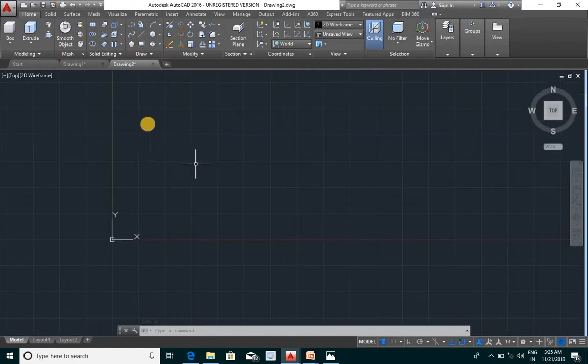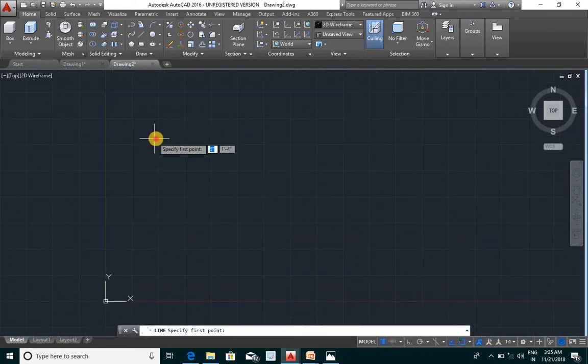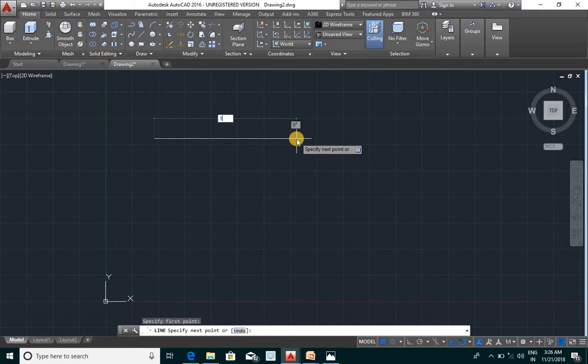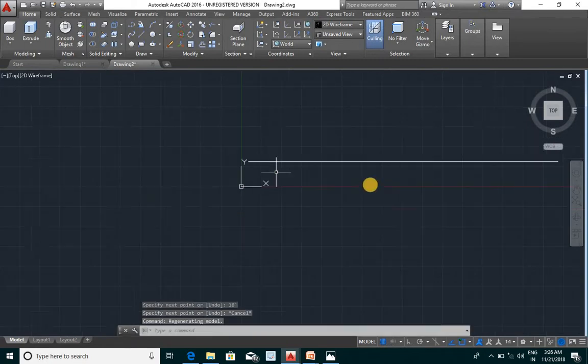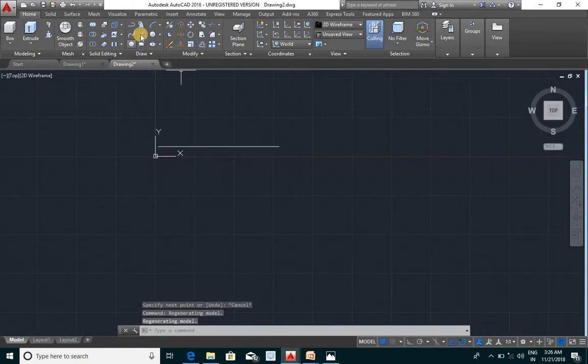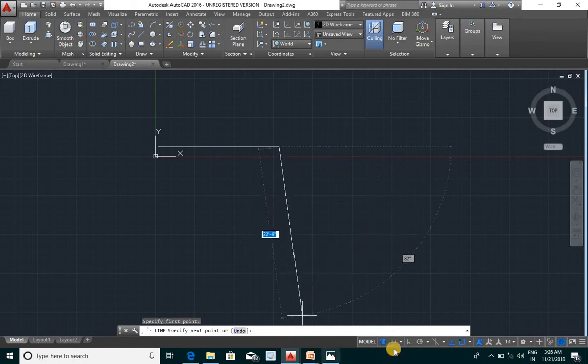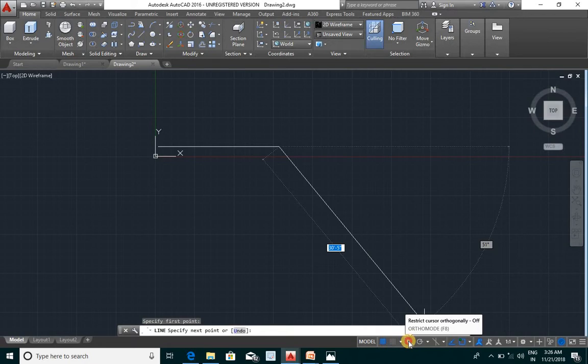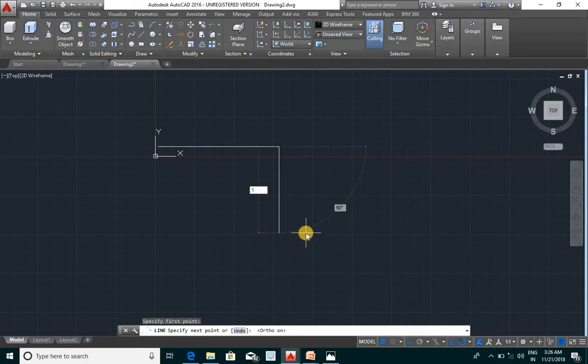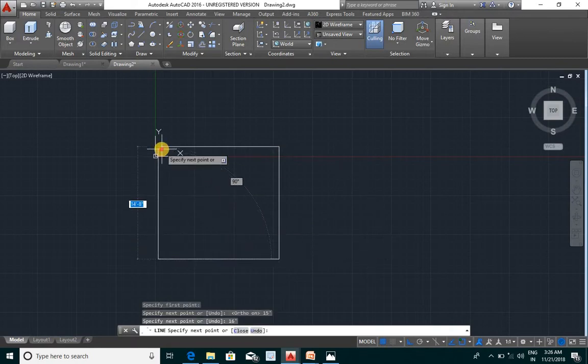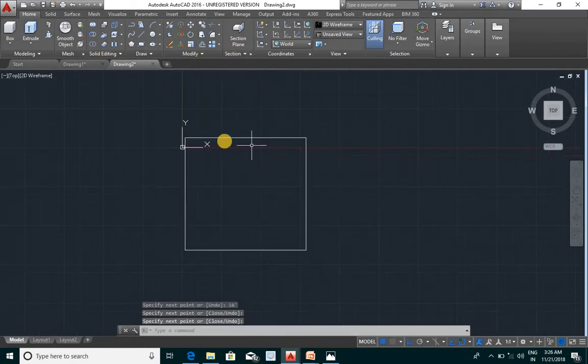Suppose you want to create a single room, and the dimension of your room is about 15 feet or 16 feet. You will create a drawing about 16 feet first. Now the next dimension is about 15 feet. You can draw a straight line by using this command. Click on this command and enter your value, 15 feet. Next one is 16 feet. Again, press here and you can join your line from here.